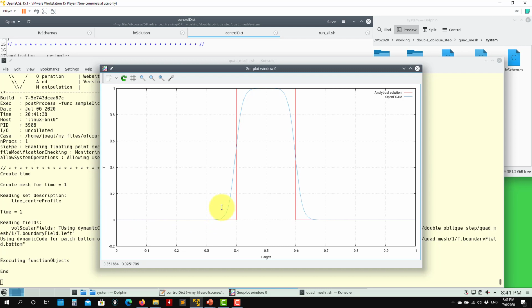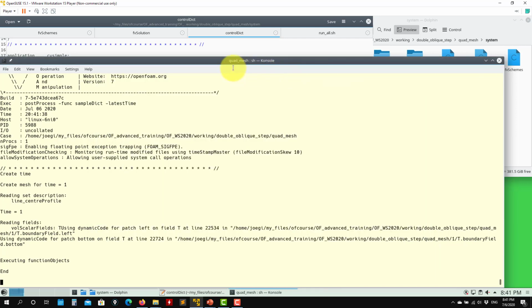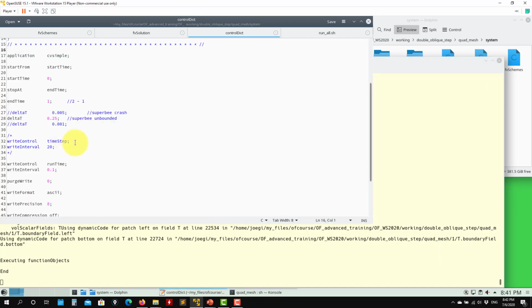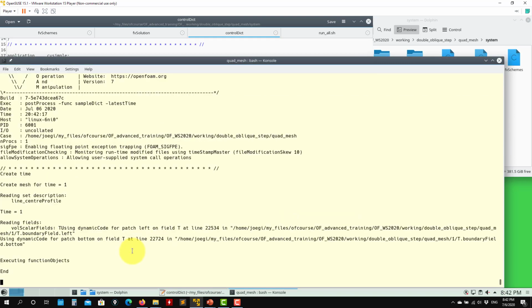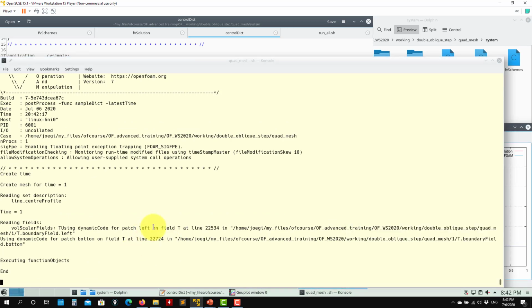But this accuracy is not because it is working well. It's just numerical diffusion that is accumulating, and here we probably have error canceling. We have some error somewhere that is canceling another error somewhere, and that is probably helping the solution to have a good agreement. So if I go here with 0.5, an extremely large time step, it should converge in iterations.